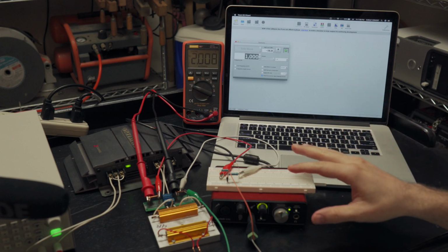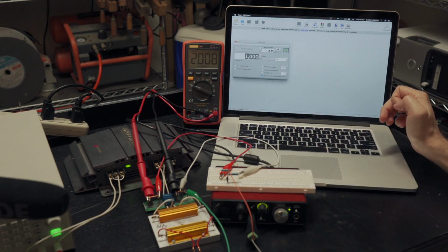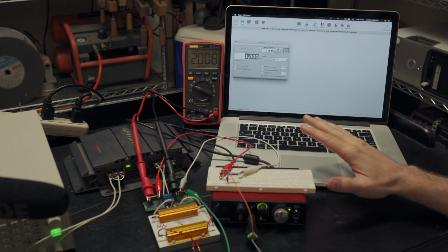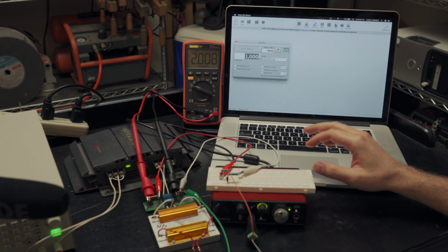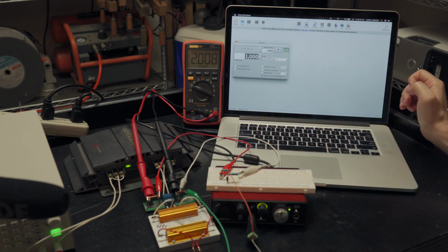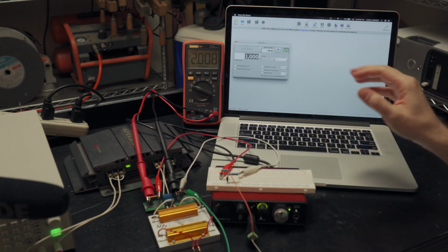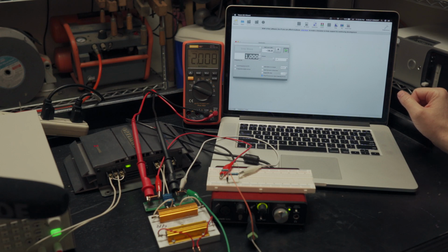This device is only going to measure up to 40K or so, okay? And so, although this is going to give us amazing measurements in the audio range, all those distortions that we were getting from those oscillations, we're not going to see any of that here. And so, if all we had was this setup, we would never know that this amplifier has oscillation and ringing problems. And that's fine. It's just different tools for different things.